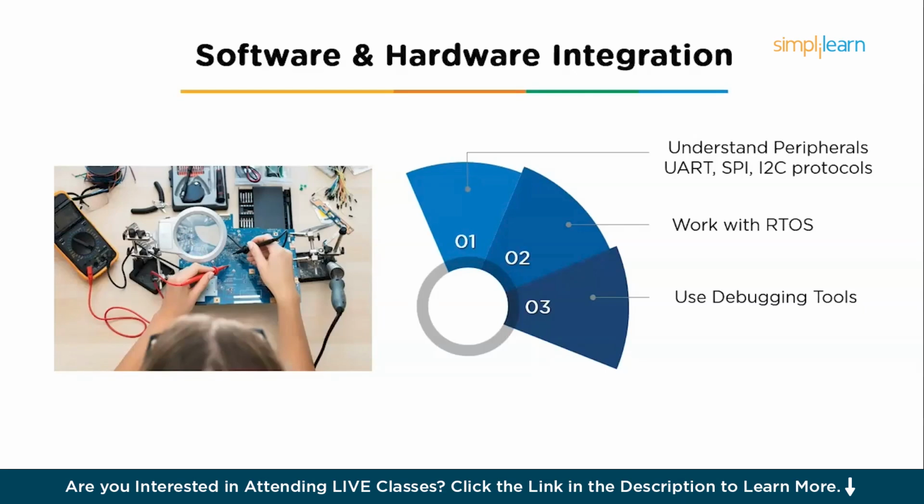You will need to learn communication protocols like UART, which is a simple serial communication. Think of it like a conversation over two wires. Then there is SPI, which is a fast data transfer, good for displays and memory chips. Then you have the I2C protocol, which is great for connecting multiple devices with just a few wires. Don't worry, each of these has plenty of tutorials on YouTube, and you could also go for courses. So guys, practice plenty of examples to get hands-on with these things.